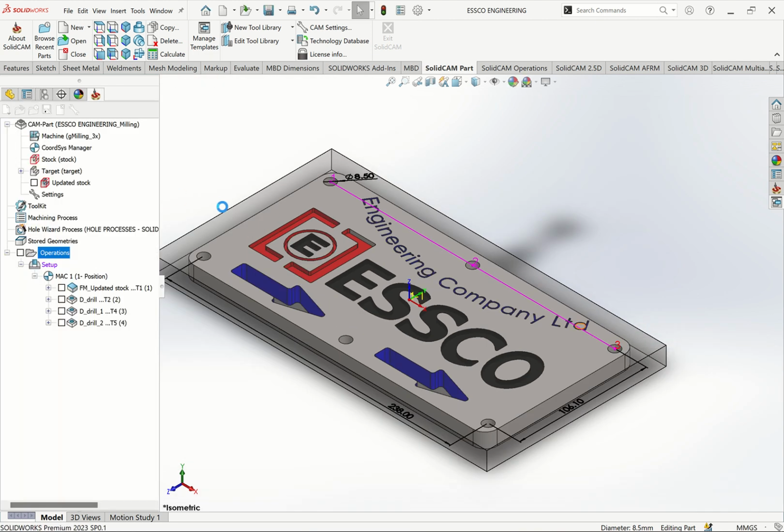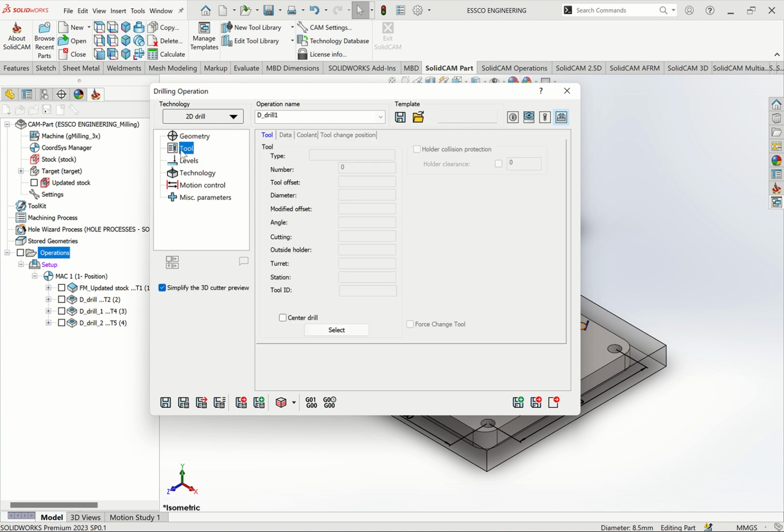I'll click on it. Again, change for the tool here. Here, the tip. Because we want to do tapping, before you go to the tool, ensure that you change here. Yes, you have these 3 of them. In case we're going to use thread milling, we change this one.